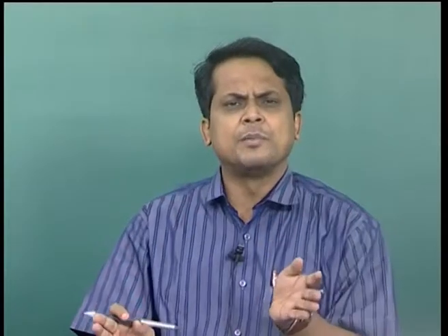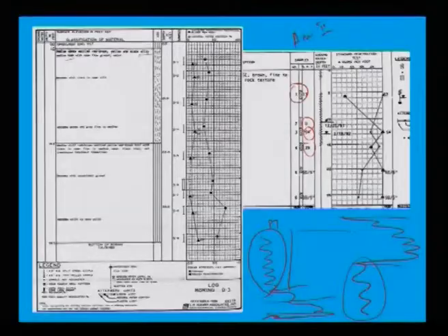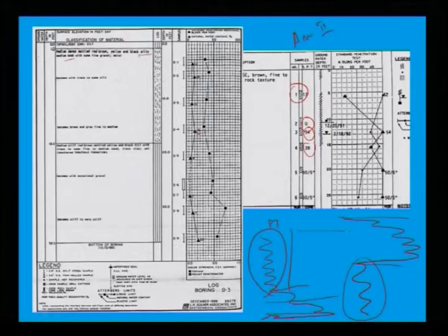Whatever field data you have, you have to show in the fourth part. The first is your laboratory summary, the fourth is your field summary. Also, if you have shear velocity data, the variation of shear velocity for dynamic properties, you show that in a diagram too. This is your fourth part. This completes how to report your laboratory test data and field test data for soft soil explorations, how the report is to be represented.